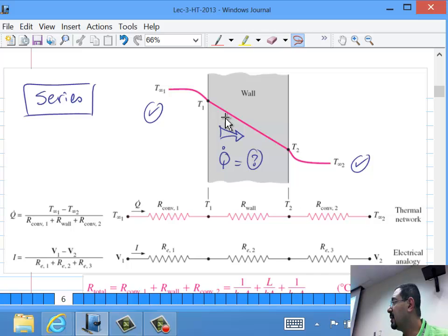If T1 and T2 were given, it would be just T equal T1 at x equal 0 and T equal T2 at x equal L. If it was convection, we used to say Q convection equals Q conduction. Excellent. Q convection, which was H multiplied by the area times this T minus this T that we don't really know, equal to Q by conduction here, which is minus K partial T partial X at this place.